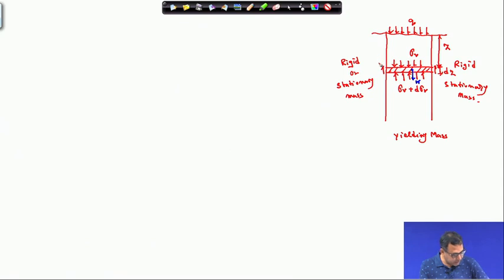This shear stress along the shear plane I can write as c plus sigma h tan phi. This is again soil against soil, which is why I have written phi. And why sigma h?